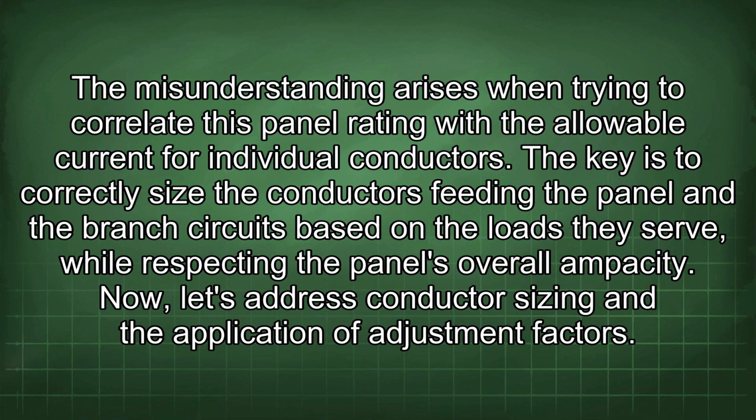The misunderstanding arises when trying to correlate this panel rating with the allowable current for individual conductors. The key is to correctly size the conductors feeding the panel and the branch circuits based on the loads they serve, while respecting the panel's overall ampacity. Now let's address conductor sizing and the application of adjustment factors.